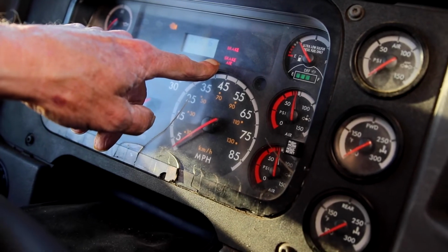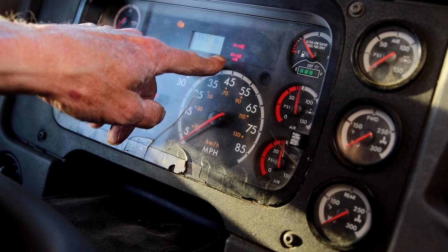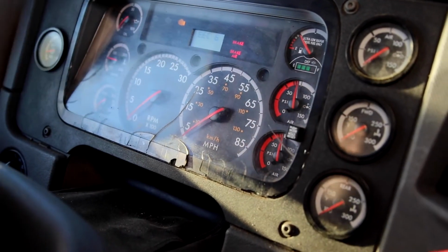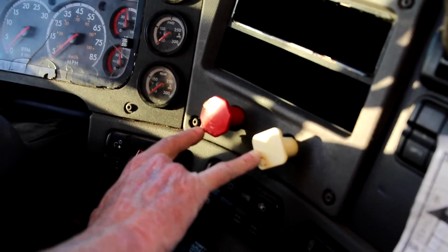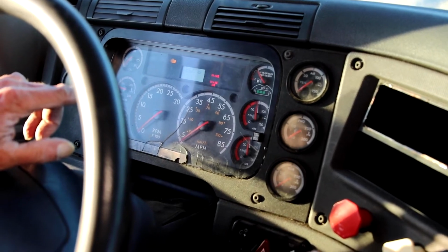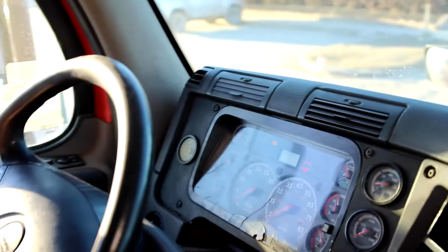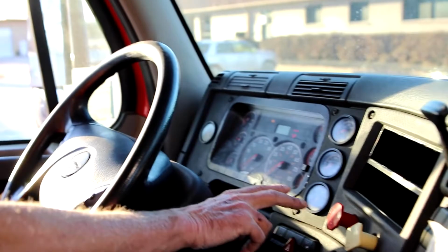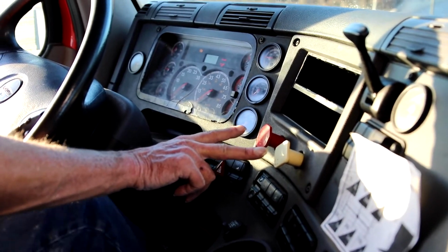The next part of my test is I'm going to fan my brakes until my spring or emergency brake valves pop out. And they should pop out between 20 and 45 pounds of air pressure. You can stay right there. Watch your valves. Make sure they pop out.